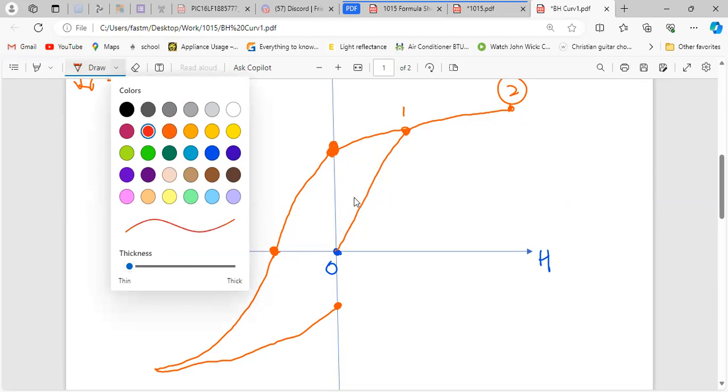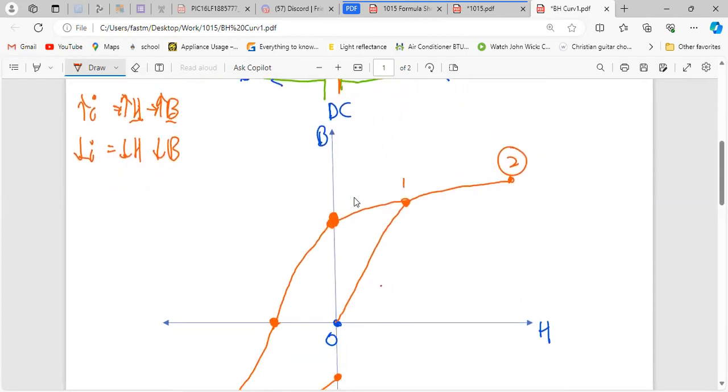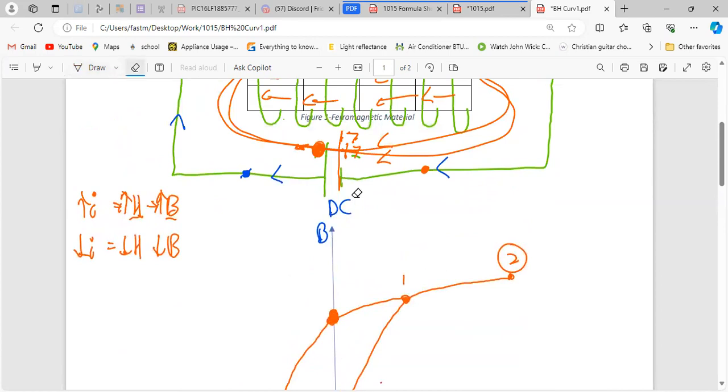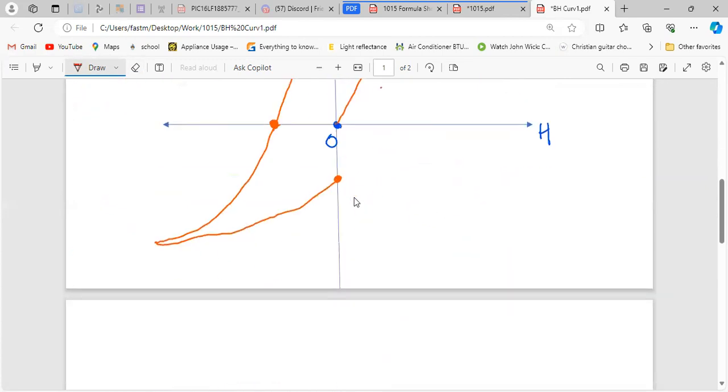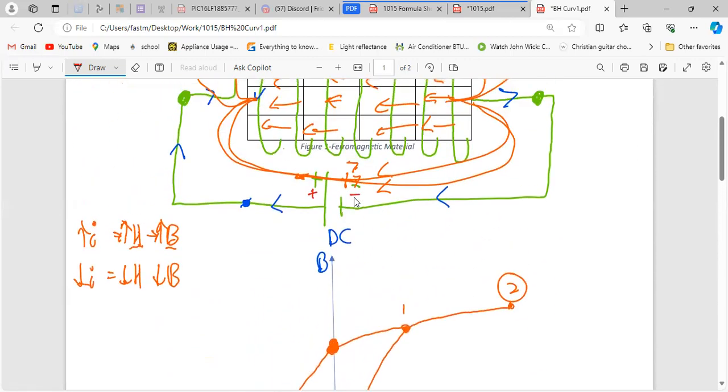If you want to remove the magnetization, same as before, you add a back current. Now we're going back to the polarity of the battery as it was before: positive here, negative here, and you add the back current. After a period of time with that connected, it will go back to being zero and the pattern will continue again.